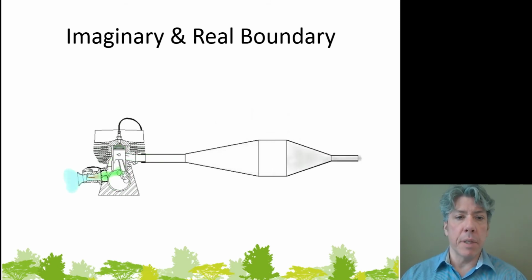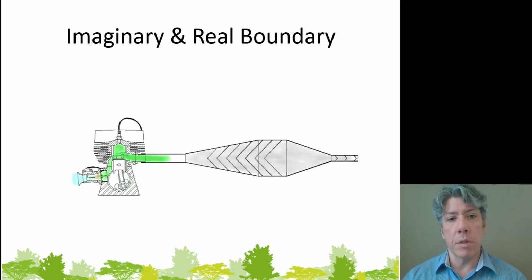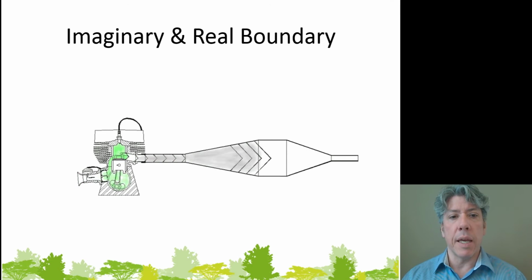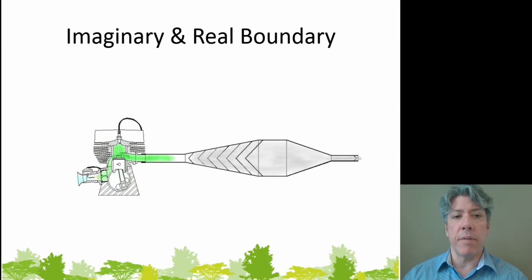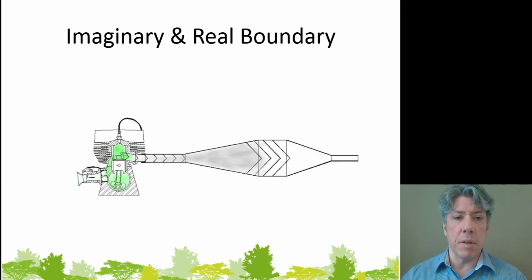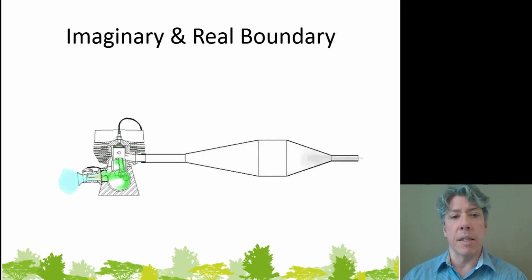Now here is an example of a two-stroke engine or two-cycle engine where there is a power stroke every single rotation of the crankshaft. One thing about two-stroke engines is that they're not particularly efficient. The gasoline doesn't have much time to burn because of the way it's set up. Instead of having intake and exhaust valves that are a separate mechanical entity, the piston serves as the intake and exhaust valve. And so there naturally is the difficulty of getting significant time for the gasoline to burn.